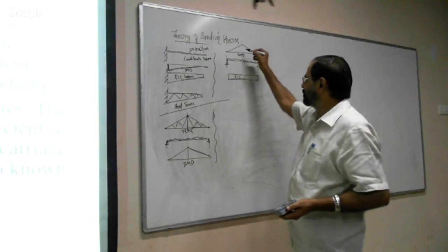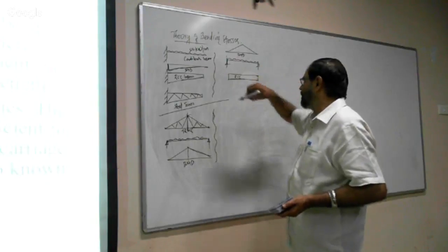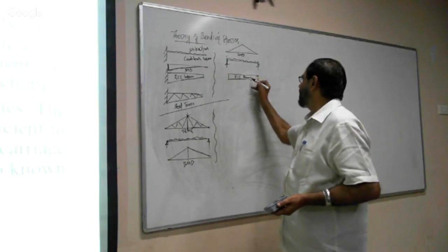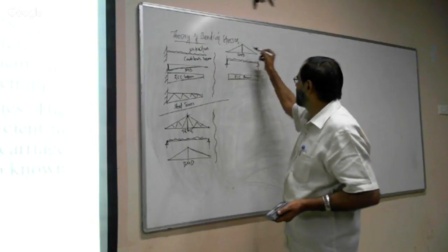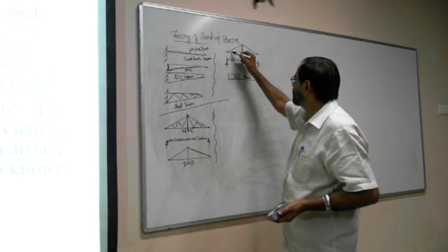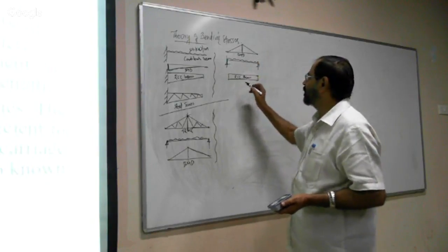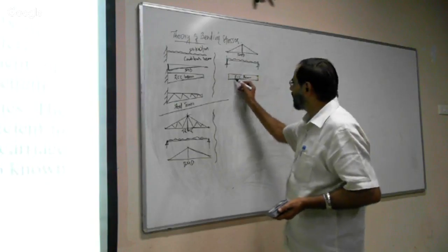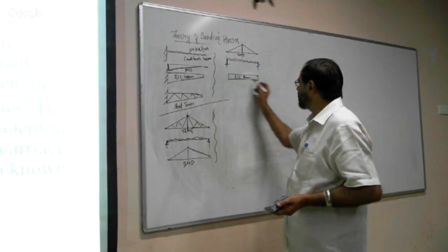Bending moment diagram, load, and this is the RCC beam. Now what we normally do: see, the bending moment is maximum here. Here the bending moment is zero. Here the bending moment is minimum. But at the time of construction, we will design the section for the maximum bending moment, and we will provide that same section throughout.